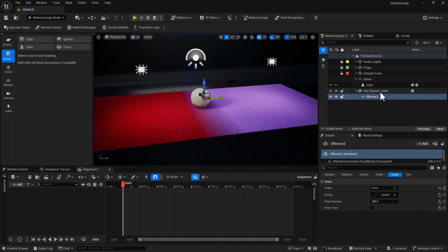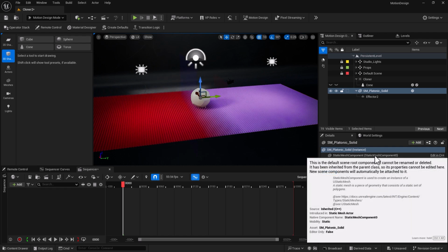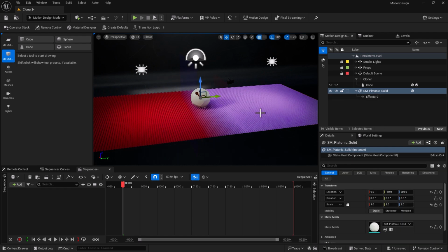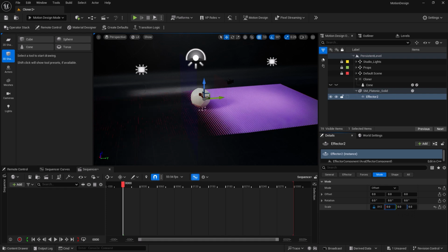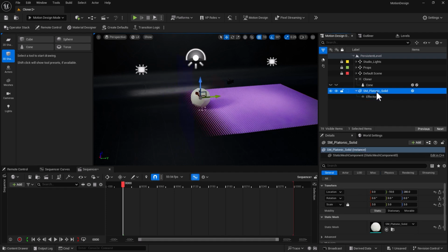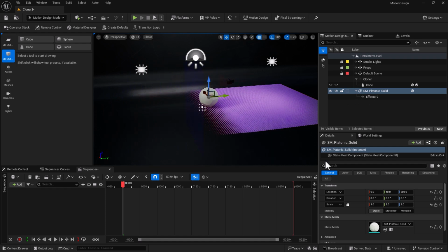But basically what this does, if I select the platonic, you can actually change the translation. Right now it's only changing the color because the color of my clone system and the color of the effector are two different colors. That's why you only see the color, but I can easily go into, let's say, mode, offset, and start messing with these attributes. Now I'm tweaking the scale value. So now if I move it, not only do I change the color, but also I'm affecting the scale value.